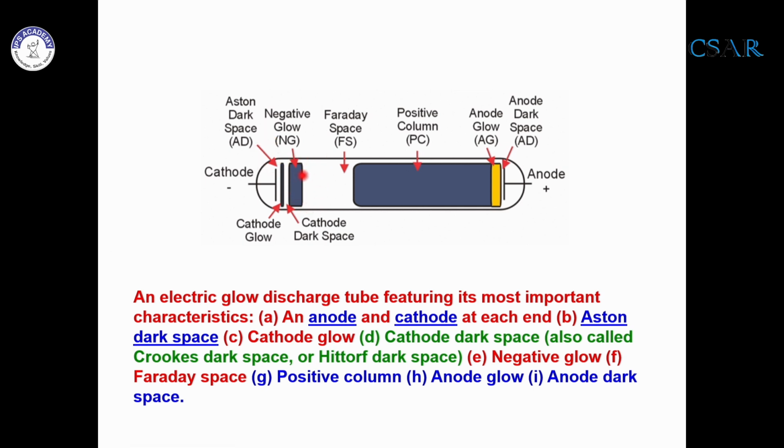In this negative glow there is a space charge, and because of the space charge there is a strong electric field between the cathode and the space charge, and the ions are dragged towards the cathode with energy, and that leads to the sputtering. And if you are doing CVD, etc., using DC discharges, which is possible for conducting coatings, this is again done at the cost of reduction in the positive column.